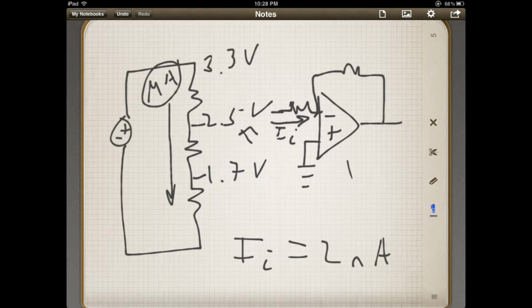But if you're dealing with, let's say, a PIC microcontroller that's doing nanowatt, or something running on batteries, you can't be hogging 500 milliamps. Because if you multiply it out and it's only a 500 milliamp hour battery, that battery's only going to last for an hour just running this chip. Or the stack of resistors, whatever that may be, representing your circuitry. So you're going to want to squeeze your circuitry as small as you can, keep it in something like microamps, so your battery life is longer when it's sitting there doing its thing.